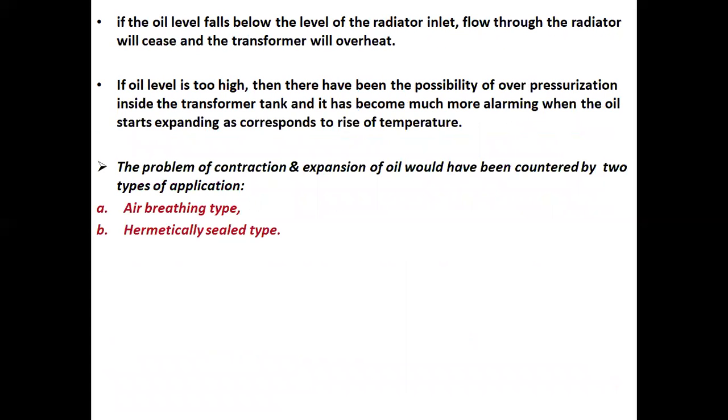If the oil level falls below the level of the radiator inlet, flow through the radiator will cease and the transformer will overheat.